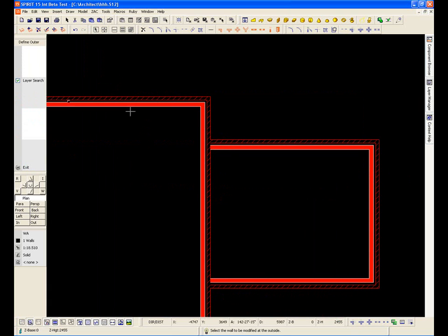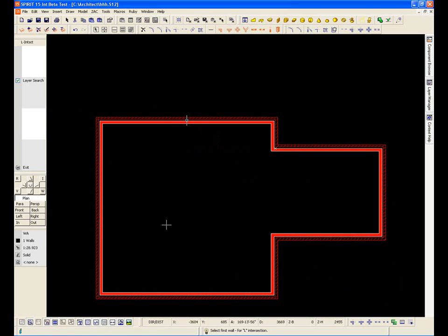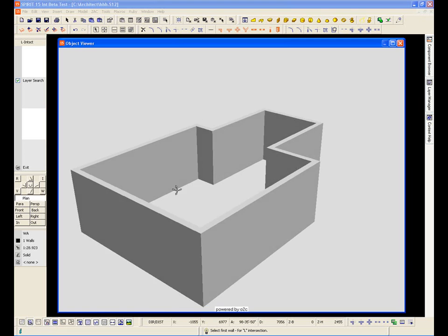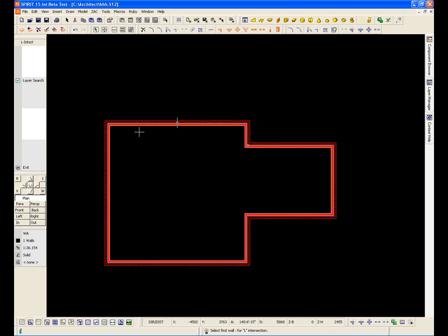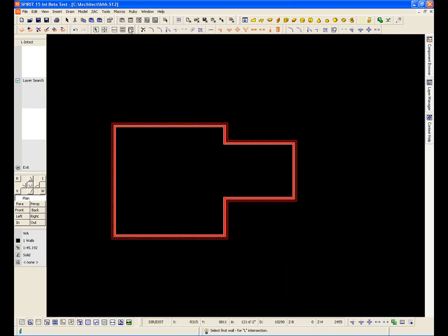I can also go to cut wall, and I want to take this piece of wall out of here and cut that, L intersect, and a bit like a two-line trim, and I can trim it up. So I've changed my wall to a brick wall. We'll have a look at that with the object viewer, and there is that particular wall in the object viewer. When I drew it, when I dragged and dropped the wall into there, if I go back to walls, architect walls, I'm using the current Z settings on my keyboard, which are, in my case, 02455.